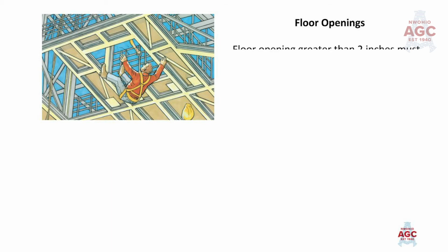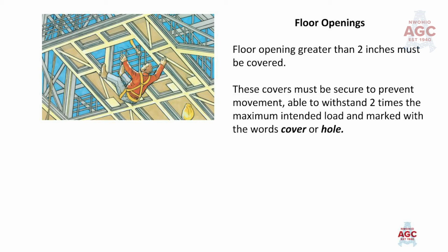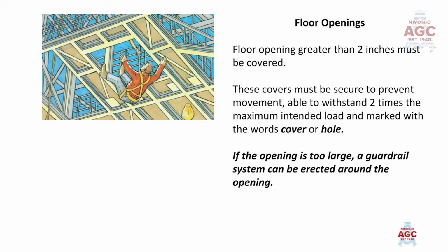Floor openings, another way to engineer the problem out. Floor openings greater than 2 inches must be covered. These covers must be secure to prevent movement and able to withstand 2 times the maximum intended load that could be placed on that floor cover. And they also must be marked with the words cover or hole. If the opening is too large, then we can simply install guardrails around that opening.